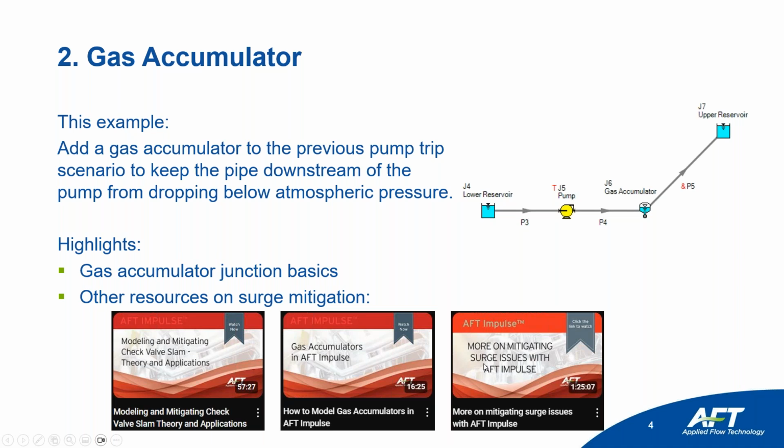If you want to learn more about surge mitigation issues over here, maybe some check valve slam, because if you remember, our pump had a combined check valve, so we likely are experiencing some form of check valve slam, and specifically gas accumulators if you're interested in those.